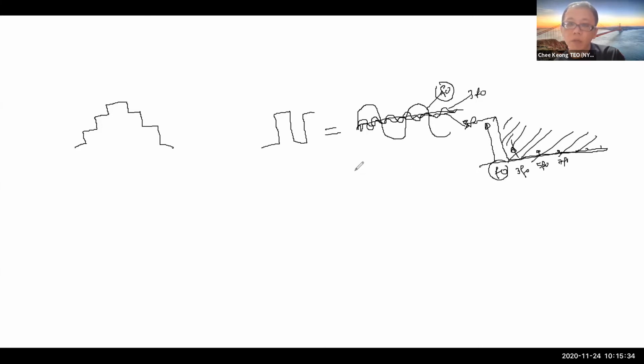So if you do a low pass filter, as a result, you will get a sine wave, which is your F0. So low pass filter is essentially the way to go to filter away all the edges, because all the edges are made up of high harmonic frequencies that, if you add up, become sharp edges here.